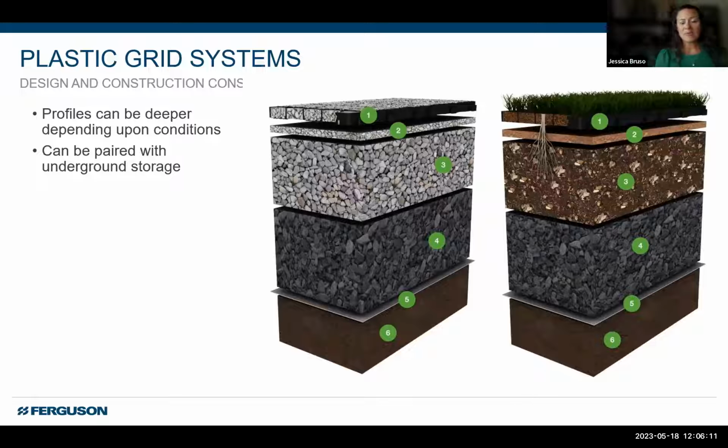Now, profiles can be deeper depending on conditions. We don't see as deep profiles here in Florida because a lot of times we have a higher groundwater table. But you can see the difference kind of between the gravel filled versus grass filled. You can actually put some more soil underneath there, do a bridging stone too if you want.